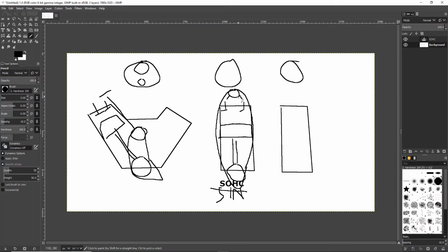In this way, because we've spread it out, we can achieve 2 intake valves and 1 little exhaust valve. And then you guys know the spark plug lives right there in the middle. So now we have less dead space and we're getting way more air and fuel in. This is a good thing. Also, look at the length of this pushrod. This would take time to translate motion and it would limit our upper RPM. Whereas with this one, if the camshaft is directly touching, opening and closing these valves, we can go a lot faster and have higher RPM. So you saw this in your 1980s and 90s Japanese inline 4-cylinders.